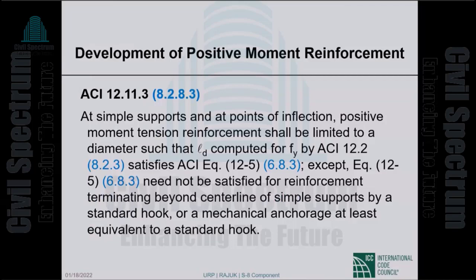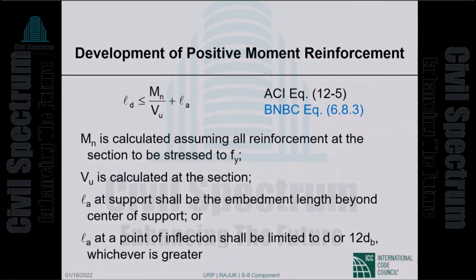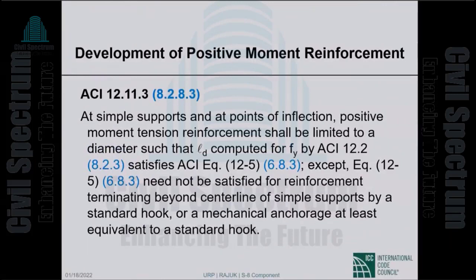At simple supports, still continuing positive reinforcement, at simple supports and at points of inflection, positive moment reinforcement shall be limited to a diameter such that L sub D, this gets a little complicated. So what we are talking about here is two locations, at simple supports and at points of inflection.